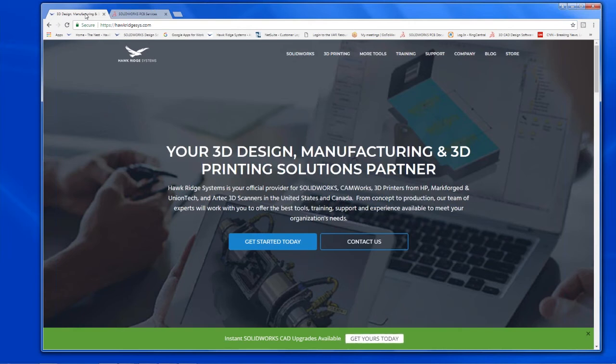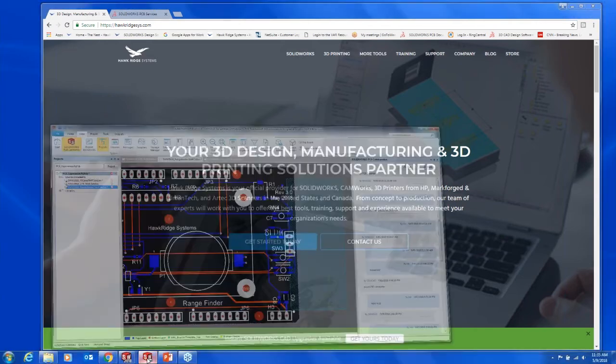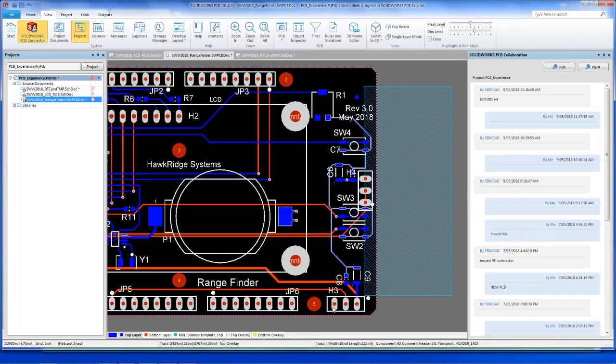Now, if you happen to move a component that has routed traces, you will see a new guide wire or a rat's nest from the end of the route to the location of the new pin. Because electronic connectivity information is not shared, therefore it's not disrupted. Altium and SOLIDWORKS PCB maintain the connectivity through the integrated workflow of the schematic and the PCB. Those two items are always in synchronization because of the project structure inside of SOLIDWORKS PCB.